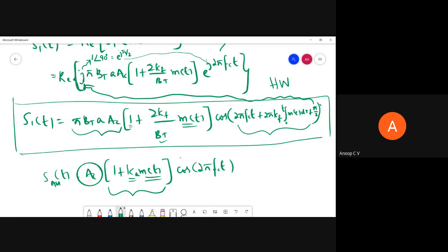Of course, right here, this is again a sort of signal with instantaneous frequency as a function of time, right? But we are not bothered about this. Whatever it is, it's a cosinusoid. Even if its frequency changes or not, what happens when you pass it through a diode? It will clip off the negative part. An envelope detector is nothing but a diode followed by a low pass filter. So whenever you pass any cosinusoid, whatever be its frequency, it will clip off the negative part, and we are interested in the envelope. We are interested in the variation of the peak values of each half cycle. So the variation of peak values of each half cycle will be determined by this particular term.